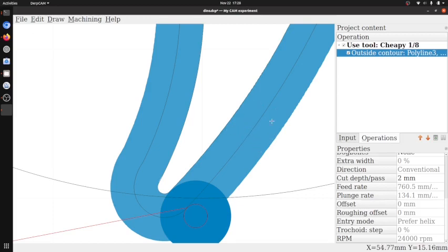The end mill is rotating and it's throwing chips back into the slot. Problem is, some of these chips aren't going to be sitting exactly in the flute. Some of them are going to be on the side of the end mill, some of them are going to be on the side of the pocket. So some of them are going to try and jam this end mill into the slot we're drilling. This kind of operation is called slot milling. It's particularly tricky with soft metals like aluminium or plastics, where you're continually recutting chips.